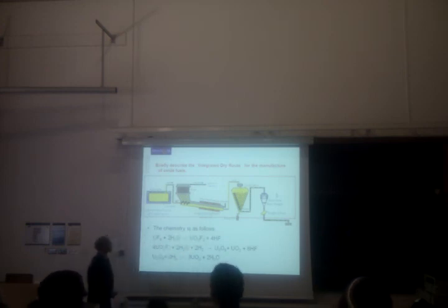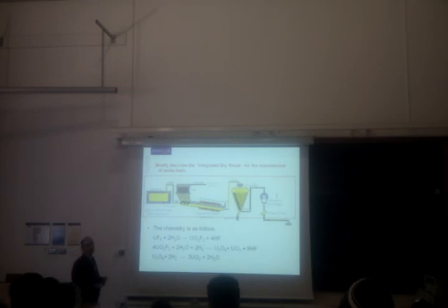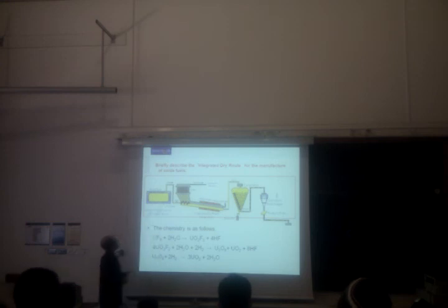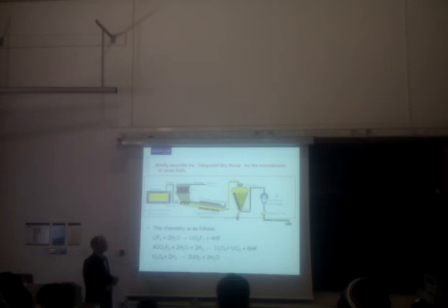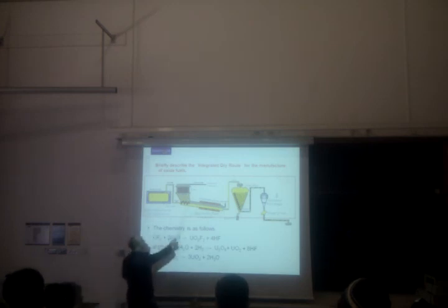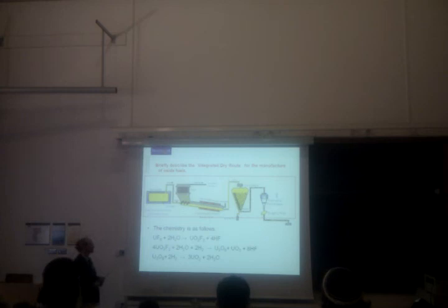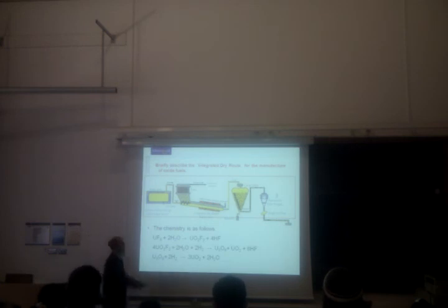So the chemistry is as follows, that's all in your sheet. All I'm looking for there is just a very brief description of the process where we take hex from an autoclave, we put it into a steam jacket, we pass it through a rotary kiln with a counterflow of hydrogen. A bit of chemistry takes place, all dry chemistry. It's not happening in an aqueous solution, it's all a dry process. And out of the other end we get water vapour and uranium dioxide.